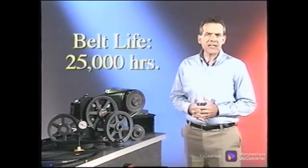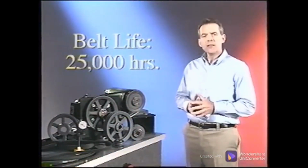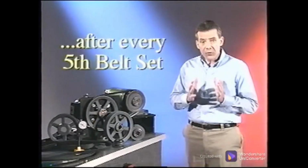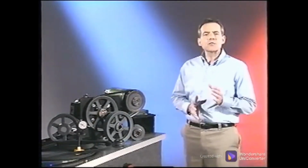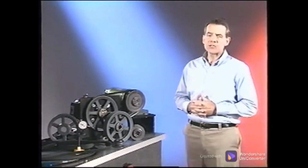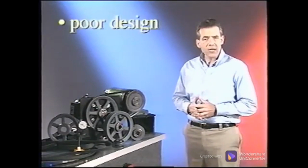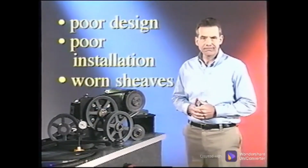Belts have a design life of 25,000 hours, or about 2 years and 10 months. Sheaves have a design life of 5 to 1. That is, they should be replaced or reworked after every fifth belt set is used. In industry today, it is common for belts to wear out much sooner, but it is assumed that the sheave will last indefinitely. When belts do not reach their expected life, the cause can be due to poor design, poor installation techniques, or even worn sheaves.